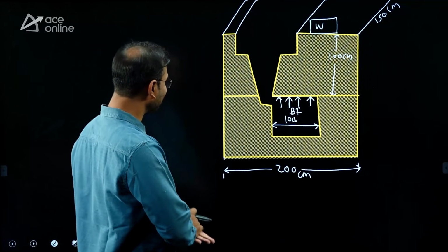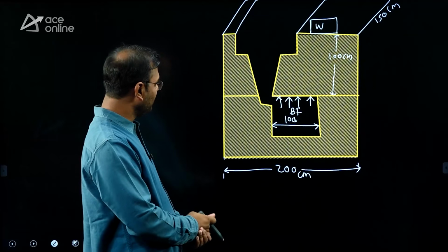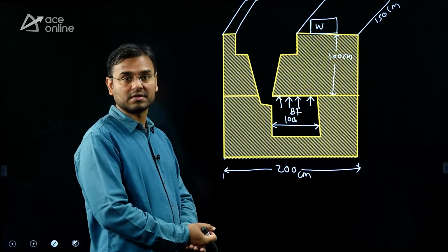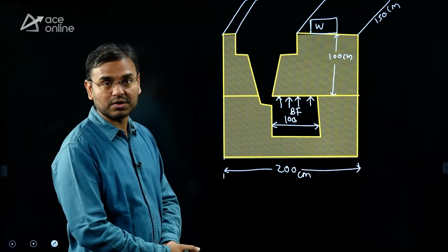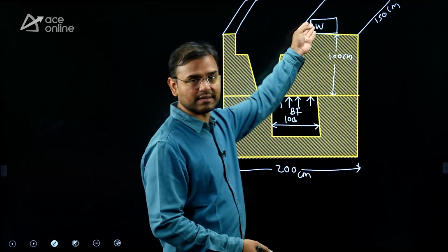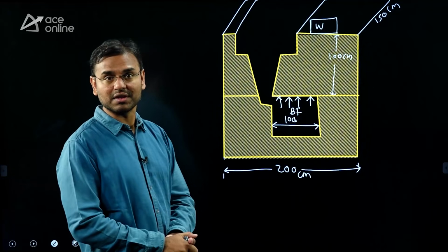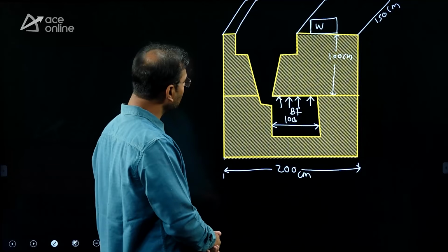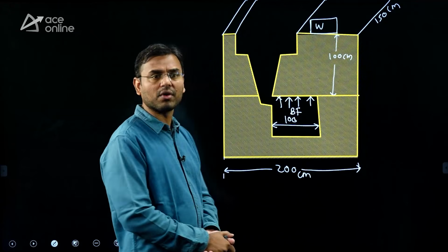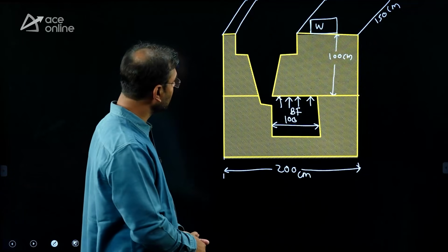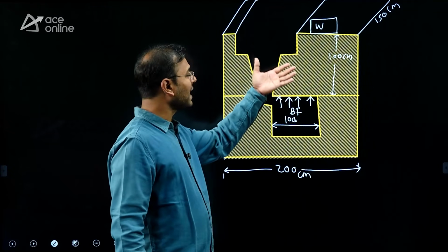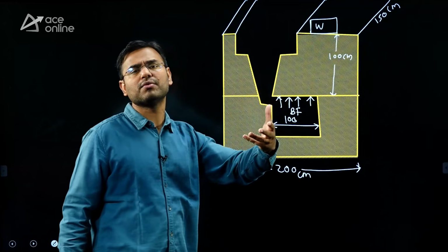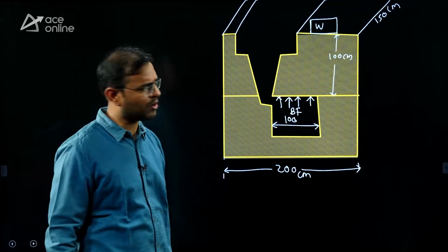Then how to solve this? Firstly, guys, what is the unit of buoyancy force? The unit of buoyancy force is Newton. What is the unit of weight, guys? The unit of weight is also Newton. Then the formula remains the same. First I will use the formula for buoyancy force, in Newton, and also I will calculate the weight of cope, because the cope also has weight, na?